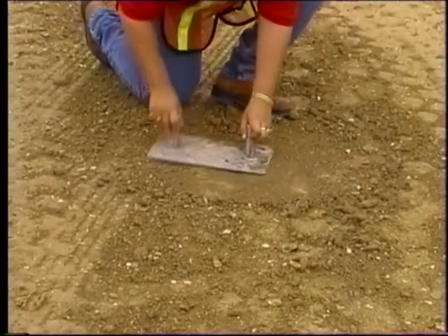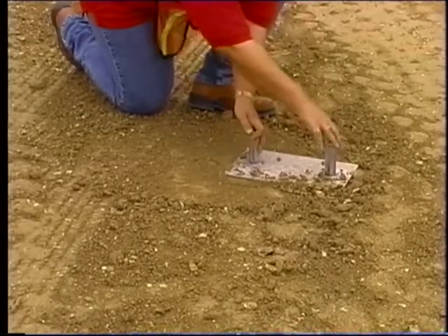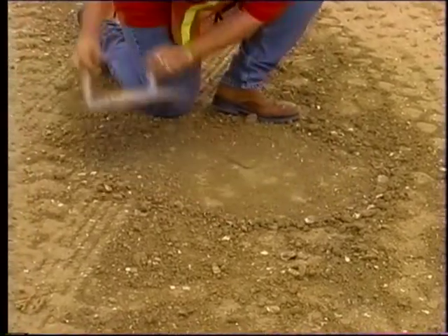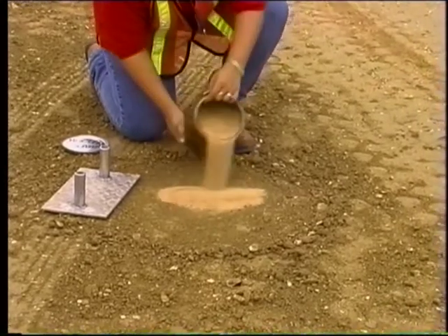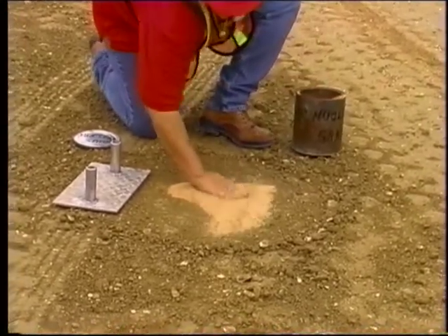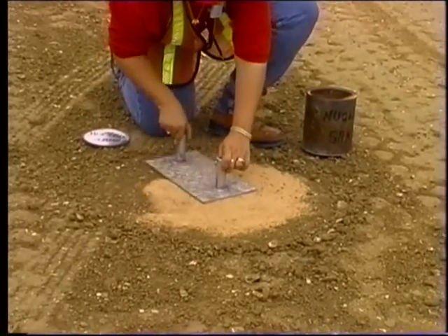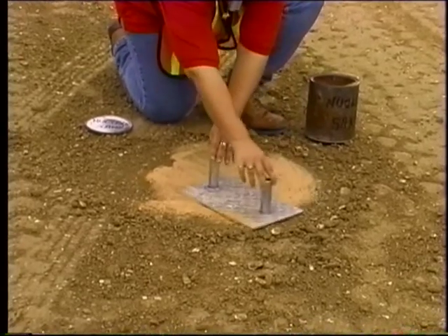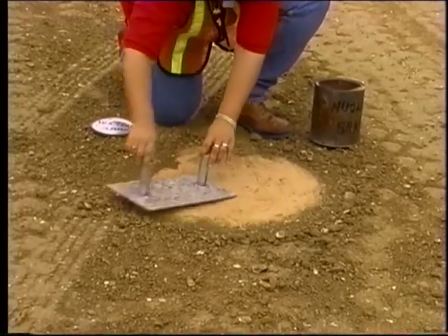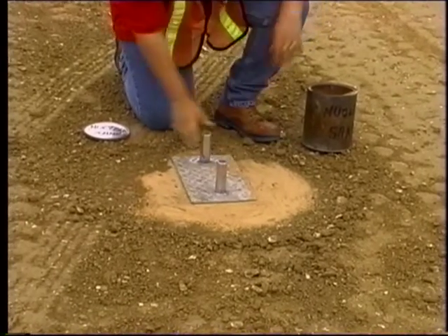Place the scraper plate on the surface to be tested and move the plate back and forth in a small area to smooth the test site. Lift the plate to remove all loose stones or surface materials and fill small voids with sand or fine material from areas near the test site. Place the scraper plate on the surface again and press down slightly to level the surface. Seat the device solidly on the prepared site with the probe at the location of the intended access hole to check the surface to see if it is prepared correctly and level.